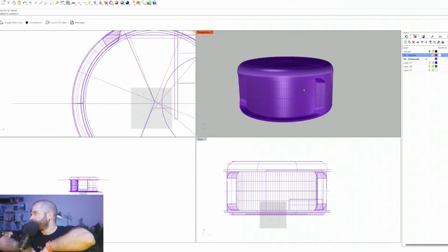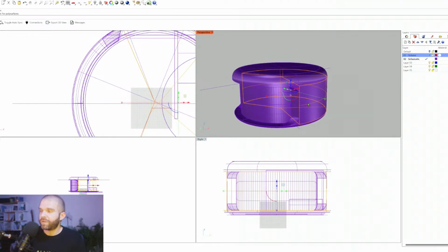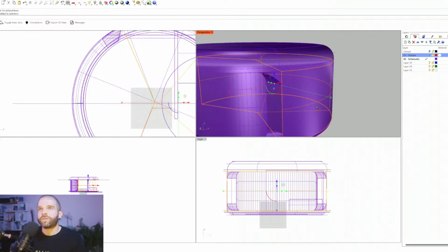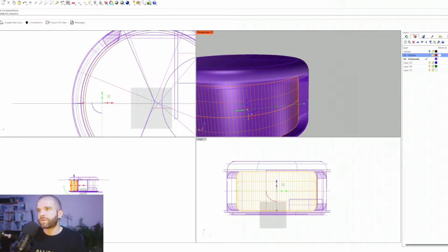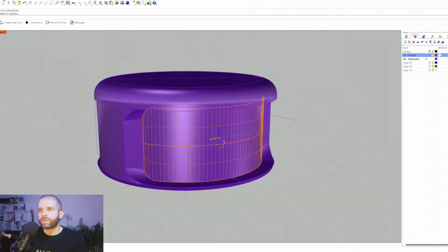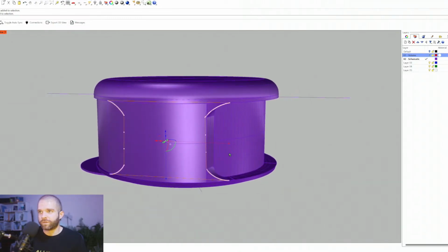When all else fails, just F10, show points, and add points and drag them to where they need to go. True, that is a sculptural approach. So if we select this object, we hit F10, turn on points for poly surfaces. I don't see it doing it for me. But I do know what you're talking about, because it does it automatically for me for curves. Like I get all the points that relate to a curve as seen right here.